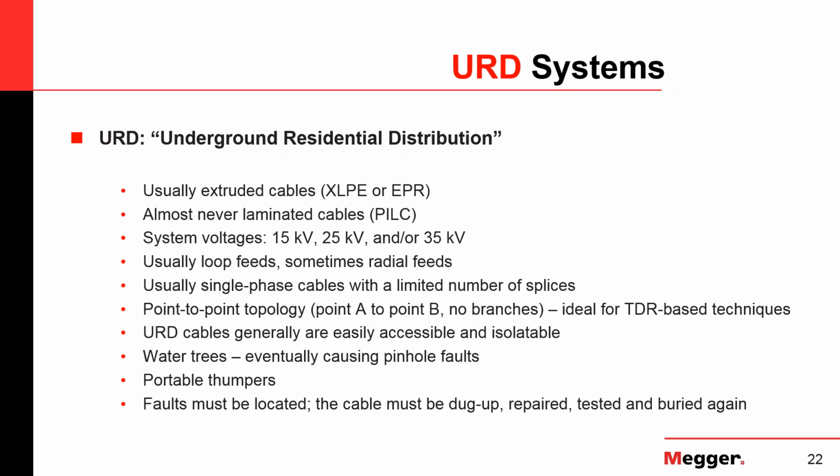The main failure mode for plastic cables, as it turned out over the decades, are so-called water trees. That means there are concentrations of water within the solid insulation, and at a certain point they will cause stress and electrical trees.